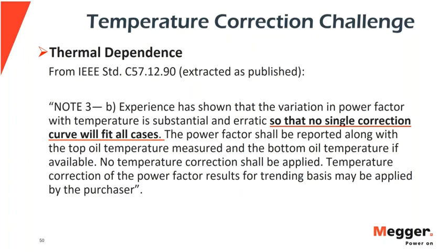On the flip side, dry type specimens are so interesting, and in the higher frequency range, up towards 500 hertz, we test dry type transformers, or suggest testing, at different test voltages, because the materials, since they are never impregnated with oil, are prone to partial discharges.